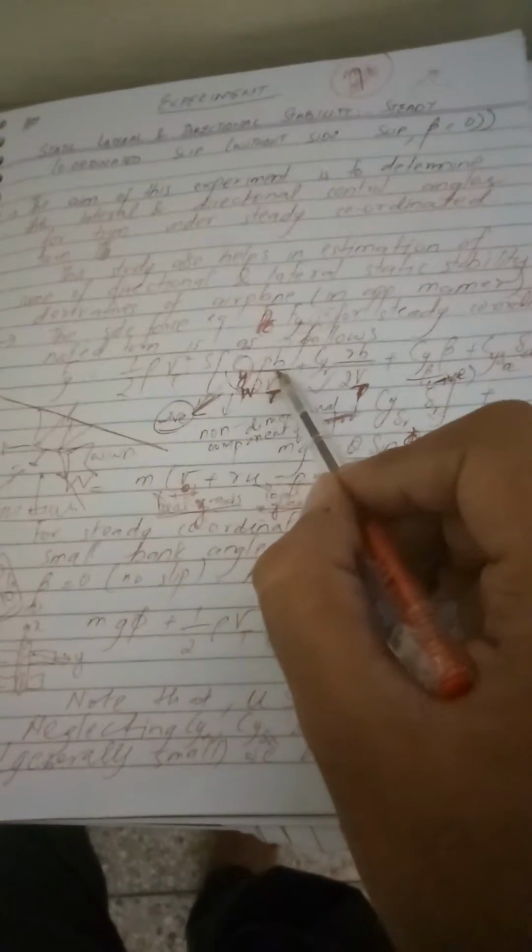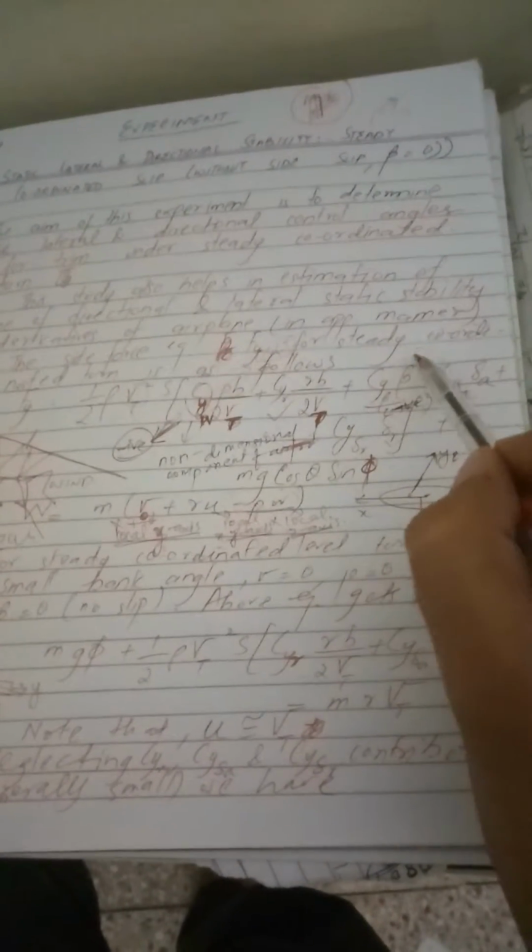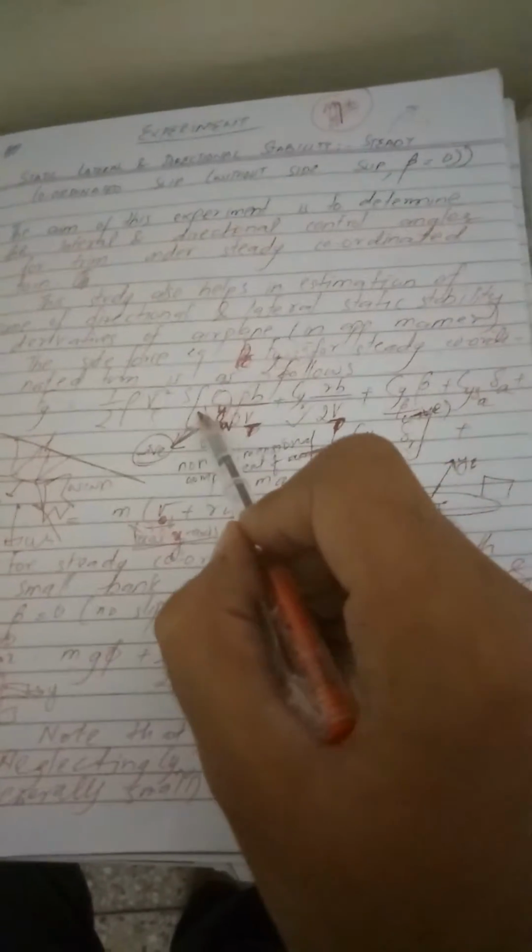Rest of the figures are absolutely near to 0. We have to ignore this one because of the steady coordinated turn. This factor is 0, and this factor would be 0 because beta is equal to 0. This factor is 0, this factor is 0. We have to ignore this one because it's very small. The only factors present would be this and this, when we're talking about the aerodynamic forces apart from this weight factor. And when we solve it out for the velocity equation, we get